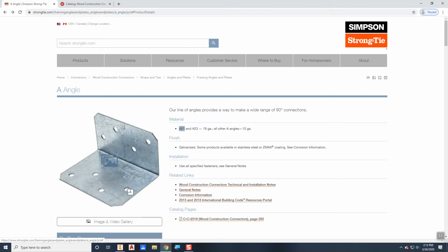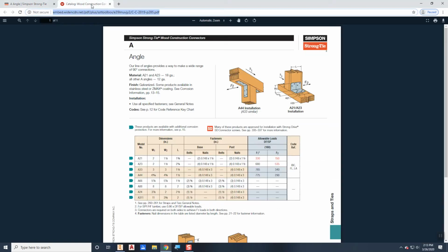It'll have 2 holes in each leg. The diameter of those holes is 5/32 of an inch, and it will be chamfered on the corners. The size of the chamfers is 1/4 of an inch. If we look at it in the catalog here and look at the example, as we zoom up on that, I can zoom up in that here.